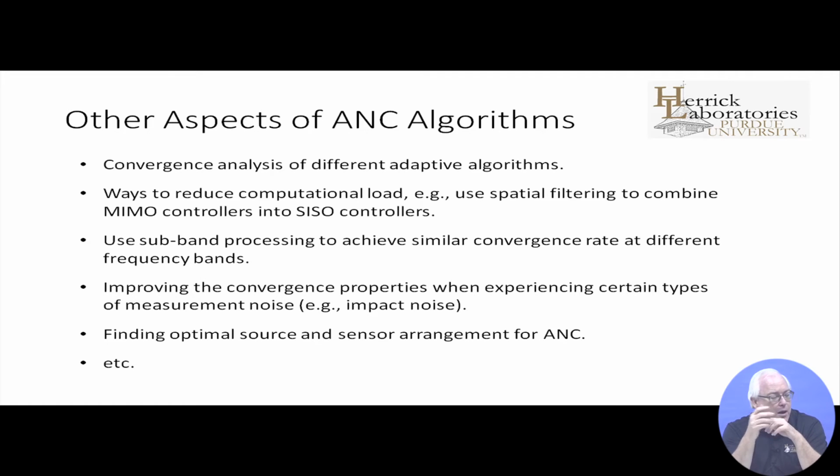And I think we're just really sort of getting to the point with active noise control where you might expect it to be able to work in a vehicle for long periods of time. But it's still a little bit fragile because it depends on the health of loudspeakers, which can be degraded over time, and the fact that all of the electronics is working properly without calibration for long periods of time. So I think there's still probably work to be done in that area.